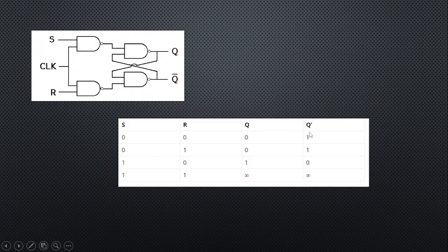So as you can see, this is the truth table. Initially, we have here, right, S and R, no inputs yet, no logic 1 yet. So Q is 0, and Q prime is 1 since they are the inverse of each other. So when input is applied to the reset, nothing happens, right? However, for the set, when we apply input to the set, it will change Q to logic 1. And meanwhile, Q prime will become 0 since, as I said again, they are the inverse.